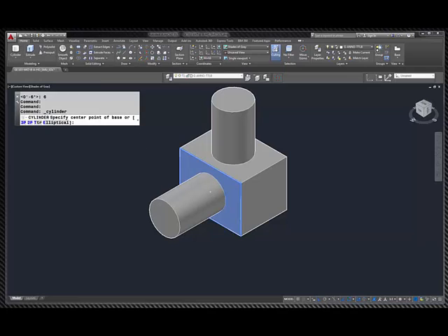Go up to cylinder, pick the face. Notice how the face highlights, turns blue. That means it's active, and you can see that my blue cursor is coming out this way. Now notice when I leave the block, the cursor jumps and goes back to world where it's standing up. But as long as you're attached to the front of that, it will stay there.